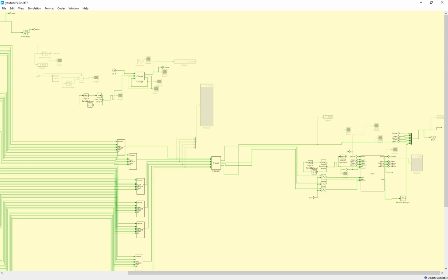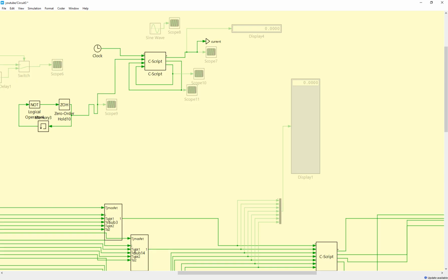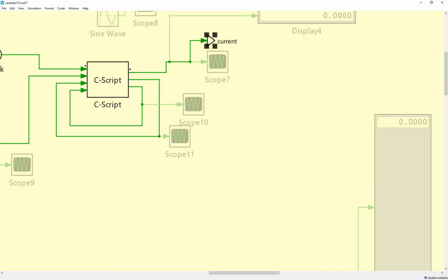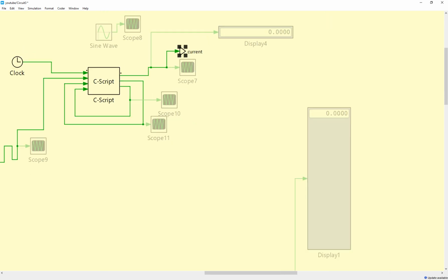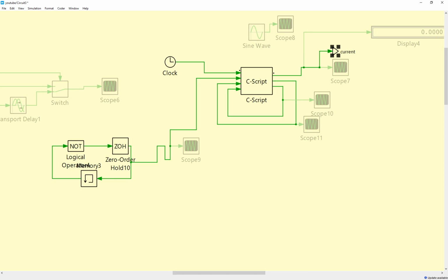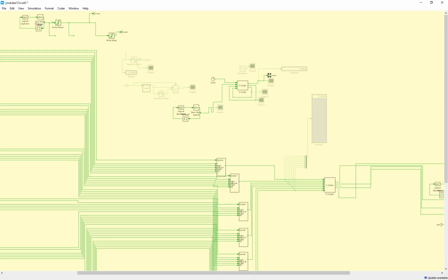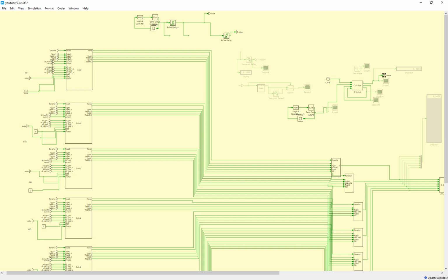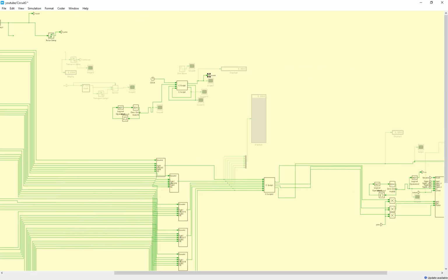And also here in the main signal, this is actually your main current. You see, I'm getting the current signal from here, a simple sine wave. Theoretically it should be a simple sine wave, but because here we have these complicated blocks calculating the model and then they're fed into the real system, there's kind of a lag here. So I had to build a complicated mechanism here to generate the correct current profile for each switching period.